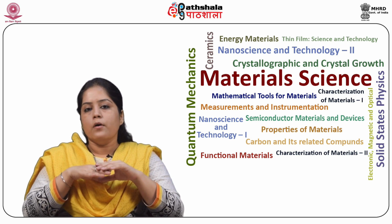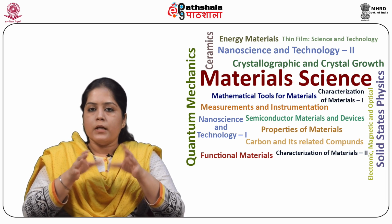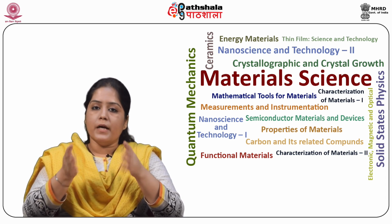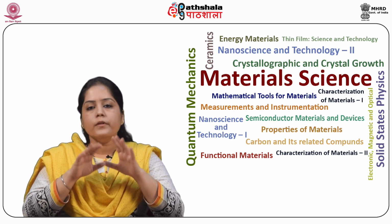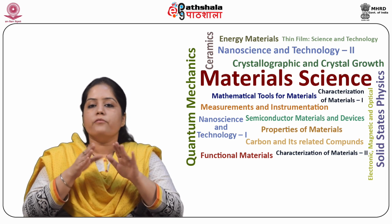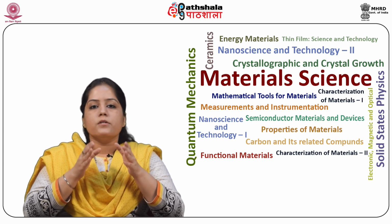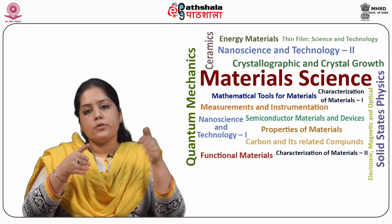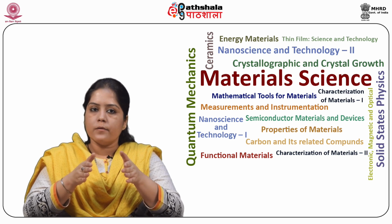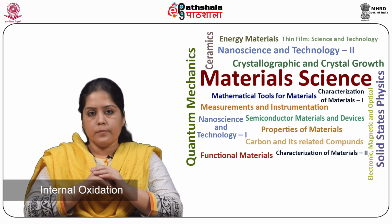At the same time, oxygen may also dissolve in the parent material, like in the case of metals such as titanium, palladium, platinum, and copper. Once oxide growth takes place by the diffusion of ions and charges in the oxide, the dissolved oxygen may penetrate into the metal, leading to the formation of oxide within it, and this process is known as internal oxidation.